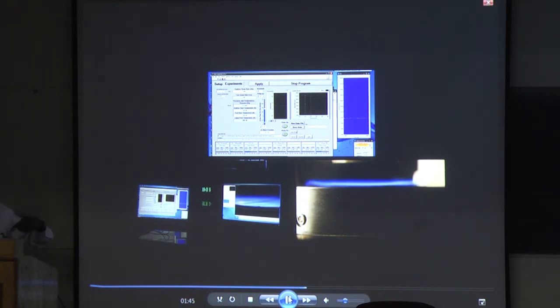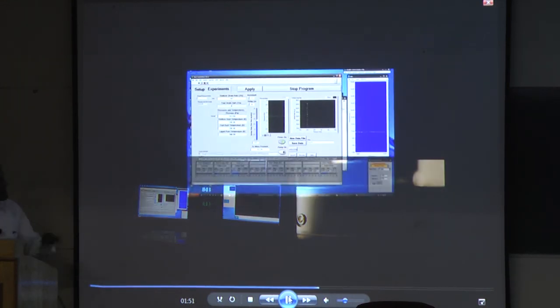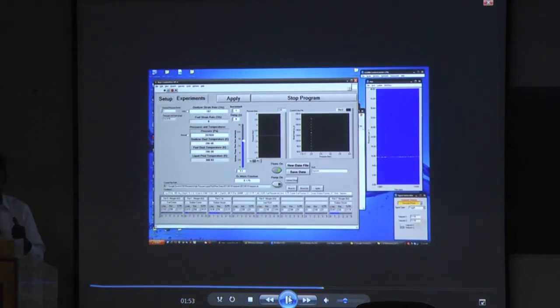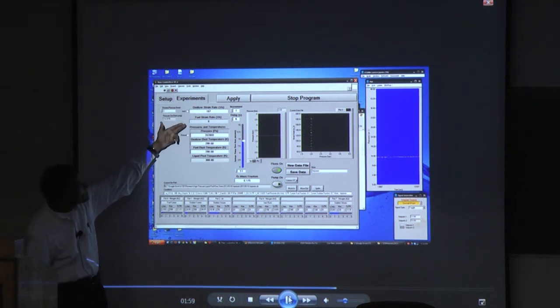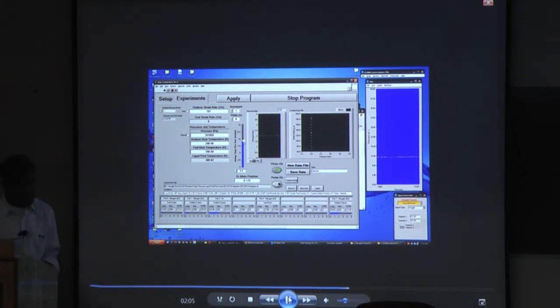So flow rates are continuously increased. So the strain is going up. Watch that. Oh, there you go. That's extinction. The flame is gone. So now we record the data, the extinction point. That's all the extinction strain rate, the oxygen mass fraction, all that is recorded. What they do is they shut off the fuel, flood it with nitrogen, so that everything is gone.